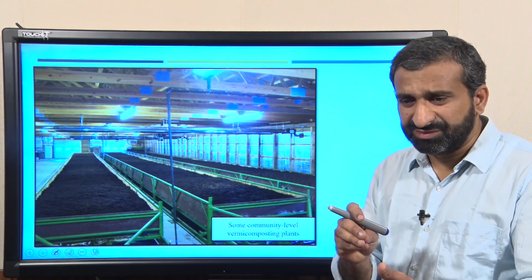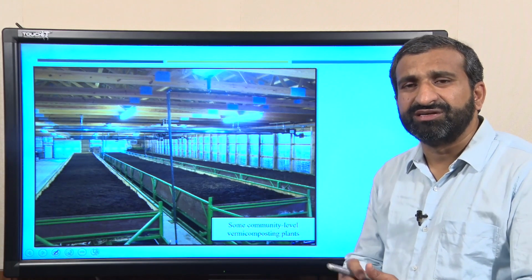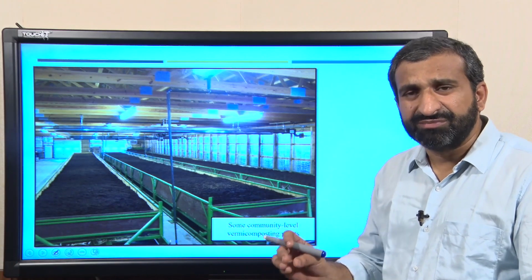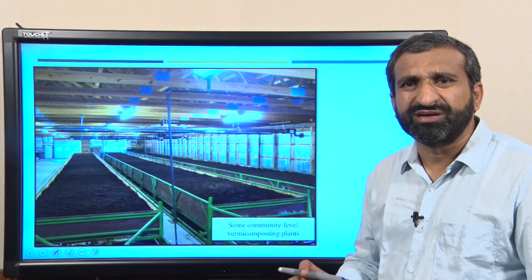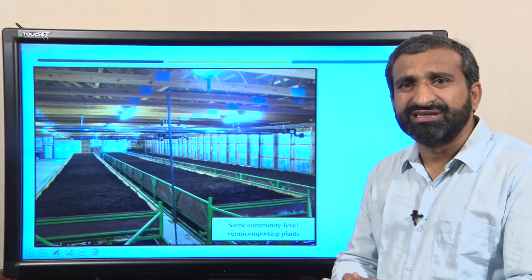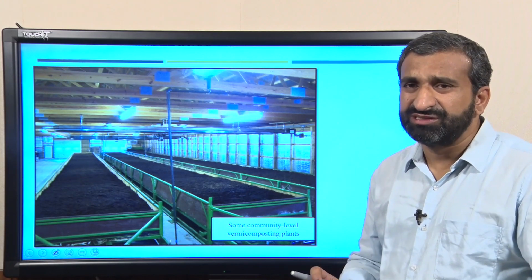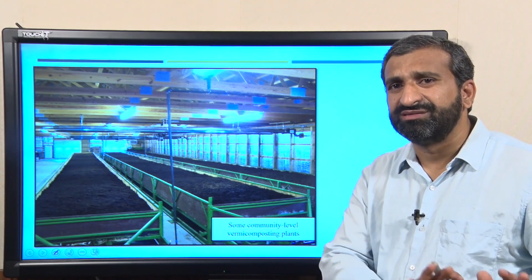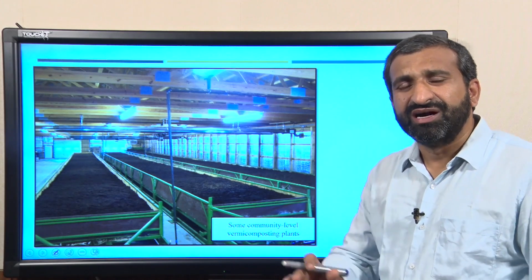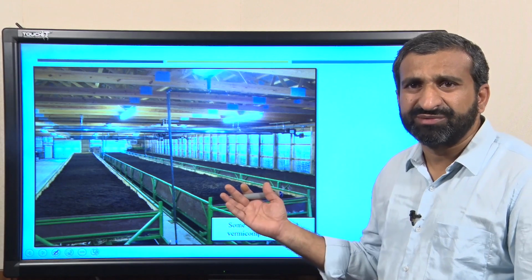because within 6 hours the degradation of this waste starts, and because of that a lot of odor issues will come up and leachate issues will come up. This leachate is also highly corrosive, which corrodes the vehicles also, and further on the disposal side also a lot of issues are coming up.